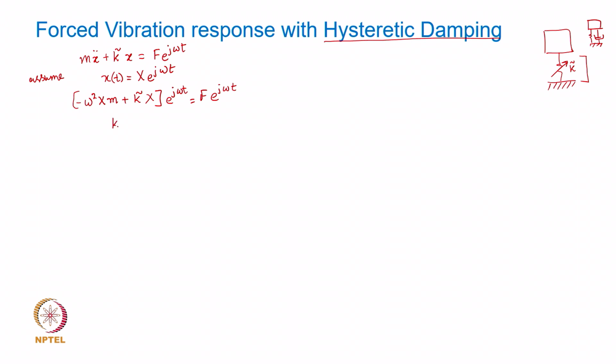You remember what is the expression for the complex stiffness? It is K, the stiffness of the material. So, if I am trying to get that for a simple beam with an end mass here, and this beam is made of steel with certain cross section, then this beam has its own stiffness, the lateral stiffness, and the damping property is captured through a parameter called what? Loss factor, yeah, structural damping coefficient, 1 plus j into beta.